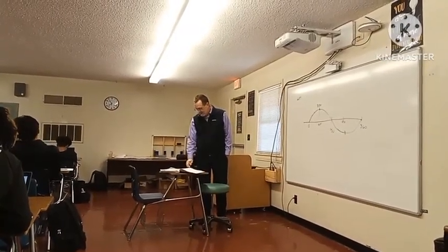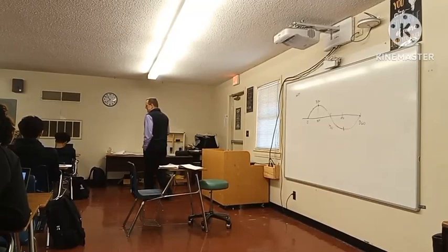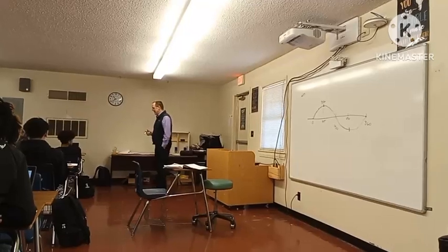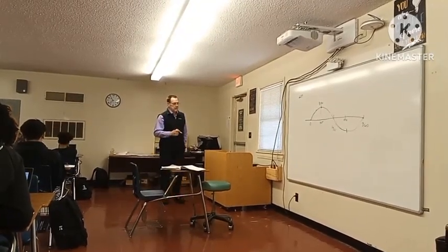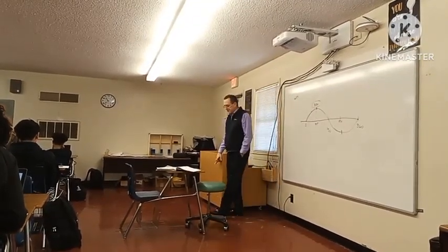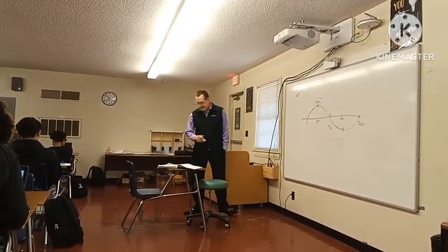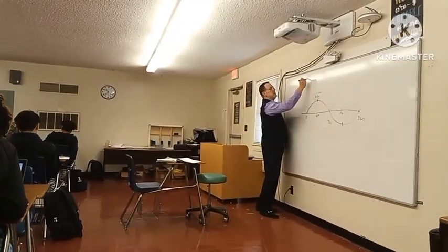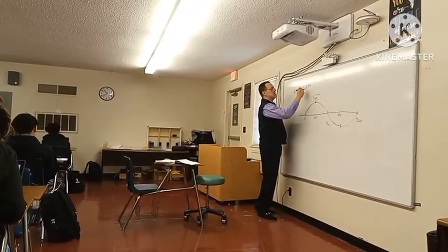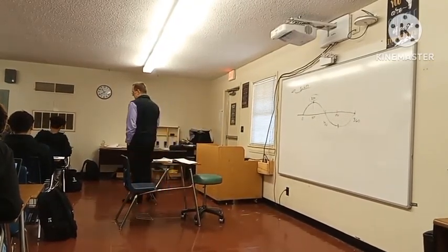Get caught up. So if we know that that's 0.637, how do we apply that 0.637 to the question that they're asking? We've got the peak value, 310. We want to know what the average voltage value is going to be, right? And that's going to be what? Let's take that 310 and multiply it times 0.637. Y'all use your technological wizardry over there and tell me what you come up with.